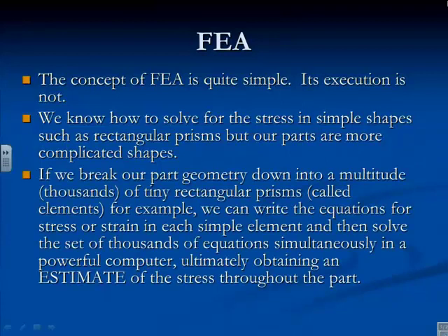But what this FEA business does is it lets us break the part down into a very large number of simple shapes, and I'll show you some of those shapes in a minute. But they essentially could be rectangular blocks, is one possibility, okay? And they're tiny. So I can put thousands of those in, and this is called a finite element, that's the name.